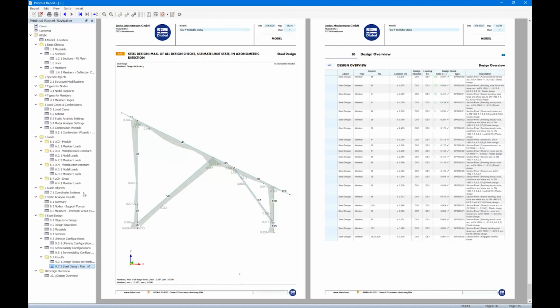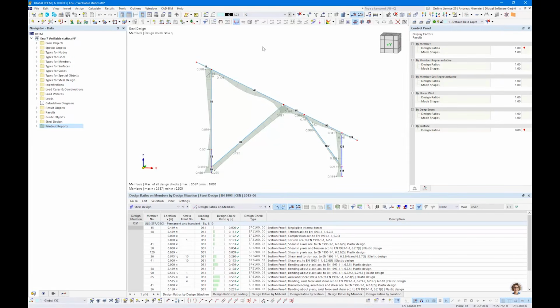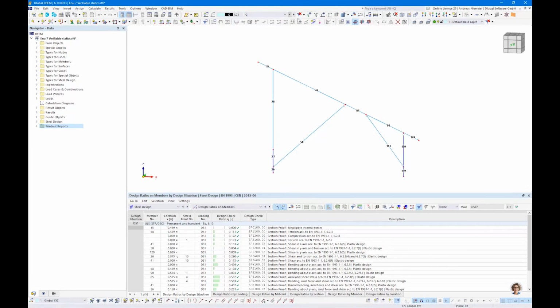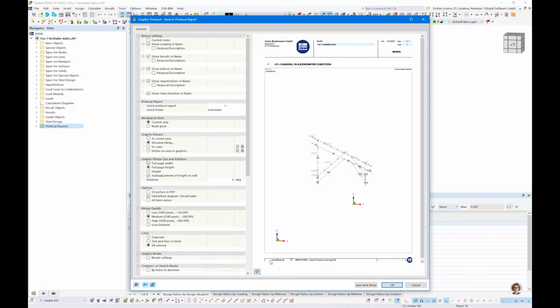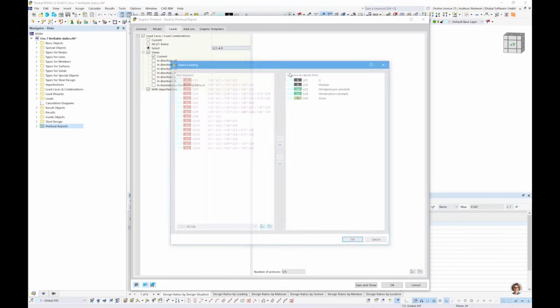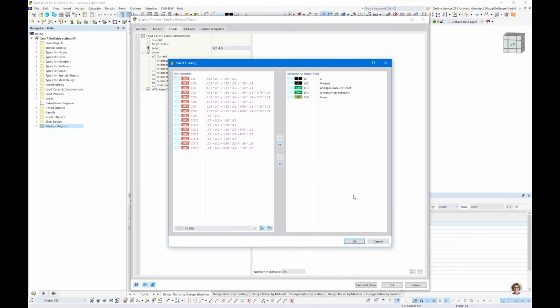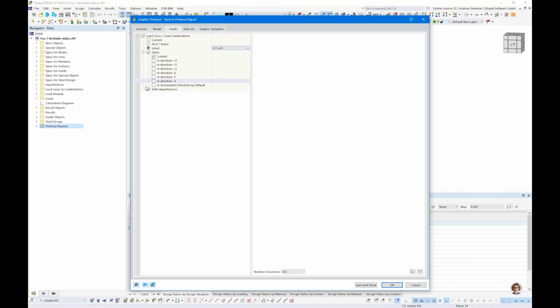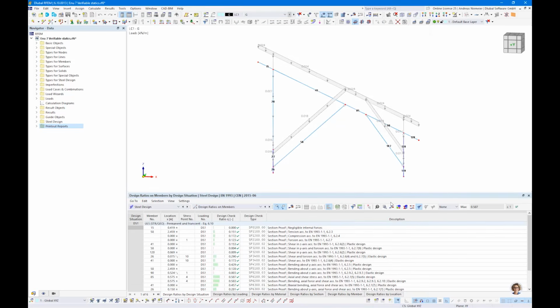No problem. If you say you need also maybe loads, then go to the printer, say I have a multi-print, no model views, only load cases, the load cases 1 to 9, only from the current view with imperfections, add-ons are not needed, and save and show.